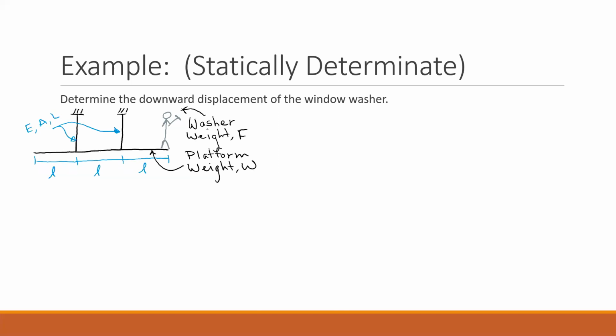Whenever we approach these problems, we want to go through each of the pillars of mechanics and materials, starting with equilibrium. So the number one thing we're going to look at is equilibrium. If it's a determinate problem, we will be able to calculate the forces in the members directly from equilibrium. If it's not, we'll find that we have too many unknowns, and then we'll move on to our next pillar of mechanics and materials, in order to get the necessary equations to solve. So for this one,